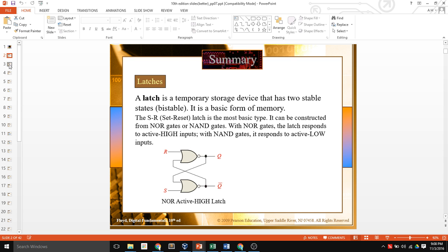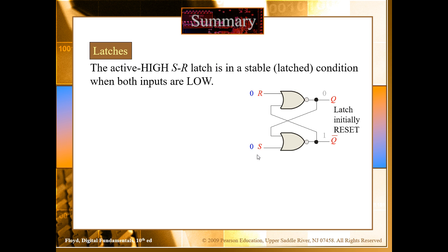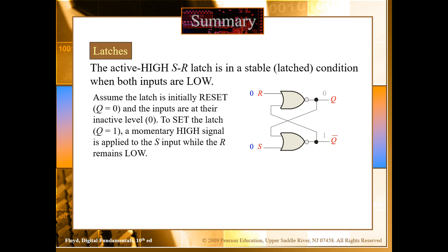What this does is it allows for a pulse to be put on our S input. And I'm going to actually run this slide because it's animated. So if I assume that we have zeros on my input, we don't really know what exists over here on my output at any given moment, unless I've put data on there. So let's just say I don't know because I just turned the circuit on. So if I have a 0 for my S and a 0 for my R, these are known as the set and the reset pins.